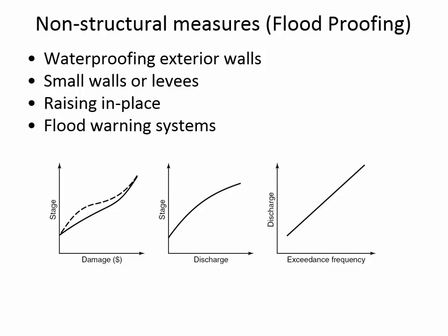All right, lastly, let's just look at this slide, floodproofing. Floodproofing is trying to use materials that can be dried out. Instead of drywall, once drywall gets wet, it's ruined, basically. It's going to get mildew and it has to be completely replaced. But there are building materials that are more resistant to flooding, like a cinder block. If a cinder block gets wet, it's not going to immediately need to be replaced.